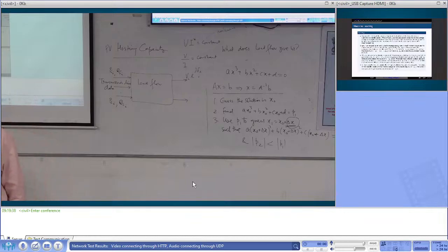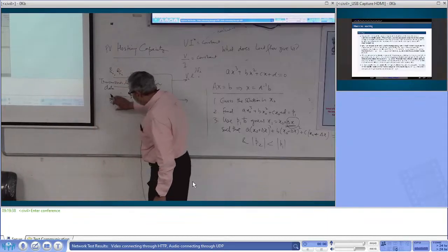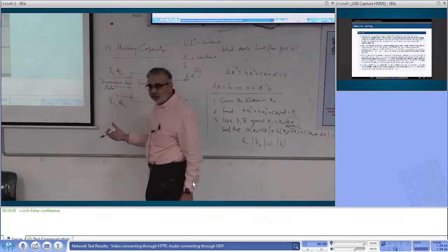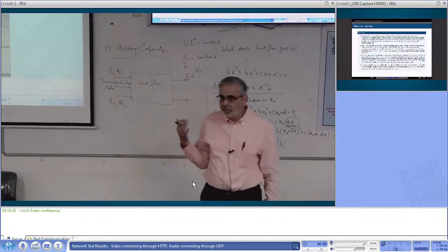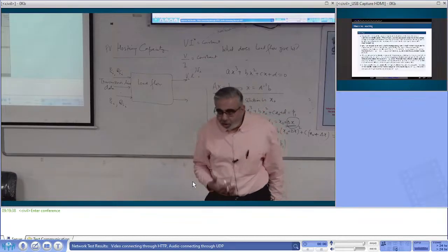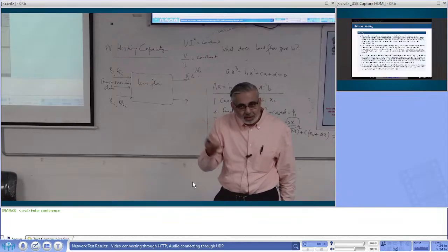What happens here is that we do not know in advance the losses in the network. So in general, this should be equal to this plus losses. But we don't know them before we do this whole business. After we do this whole business, we will find out that there is a deficiency in power.